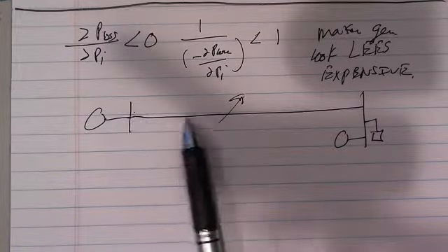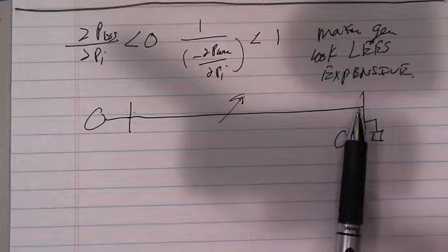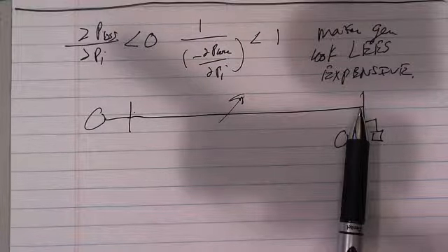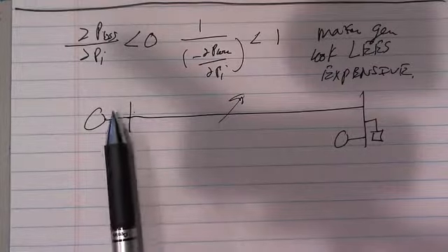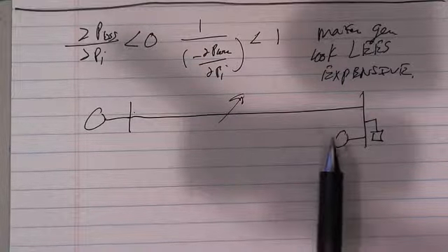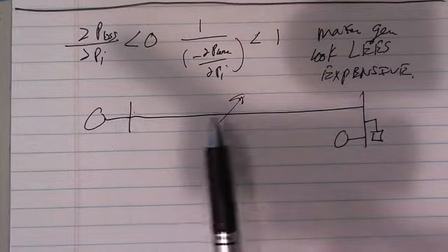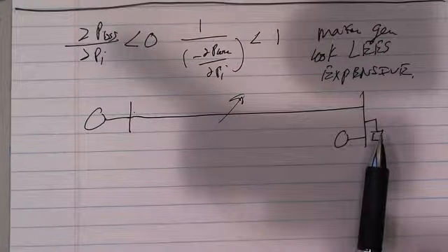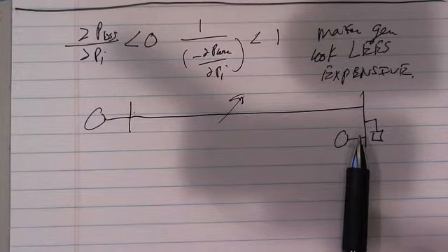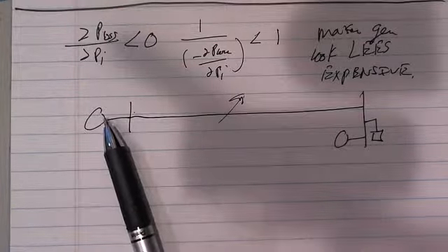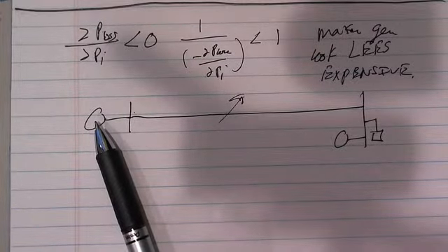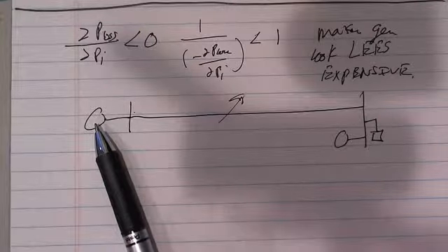If I wanted 250 megawatts here, and these are identical generators in that example, each 500 megawatts as I recall, and I want 250 from here and 250 from here, well, then I've got to supply 260 or whatever the losses are here. What's that cost?